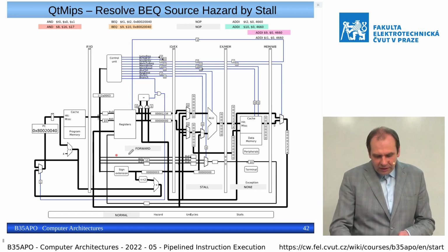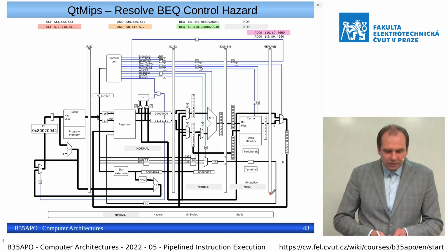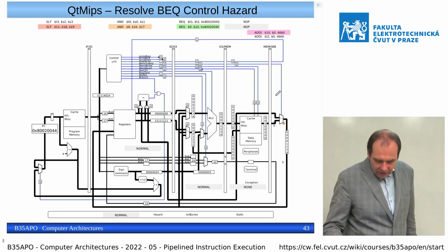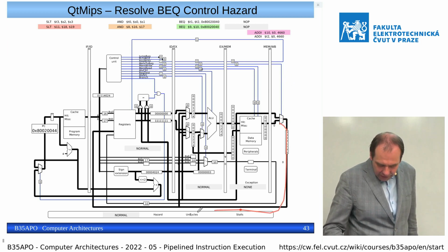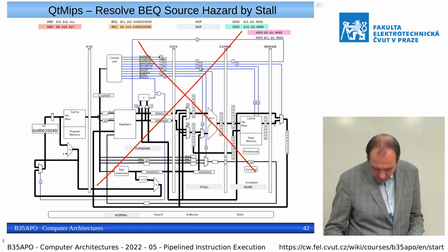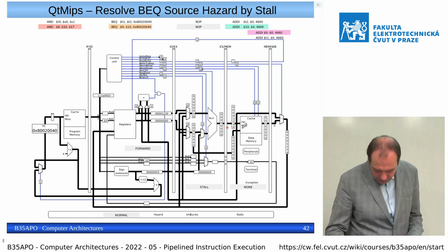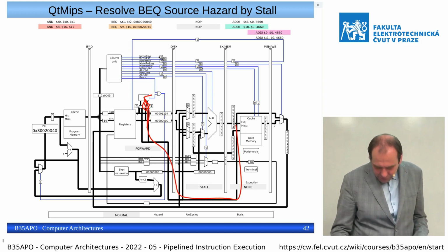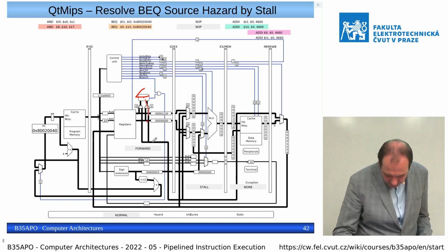So it is quite complex, but you can be happy that we have switched to RISC-V, so you will not see MIPS in the exam. It is easier. So what happens here is that we can forward the value from write back to the... no, it was forwarded one clock before. It was forwarded now from here. It should be forwarded, yes, this one. There you can see that the input to the comparator is switched to this forwarded path.